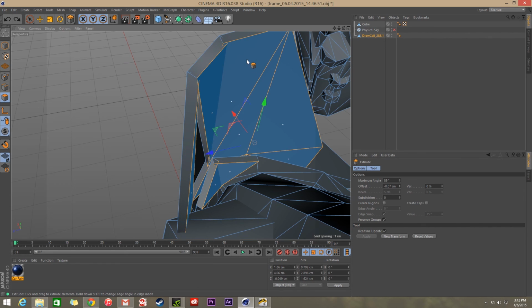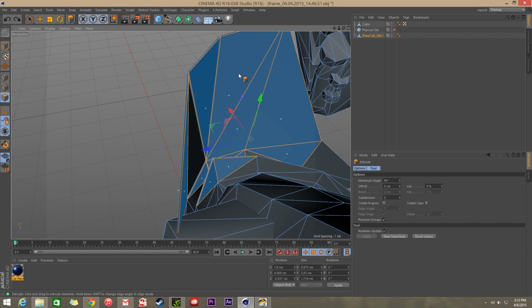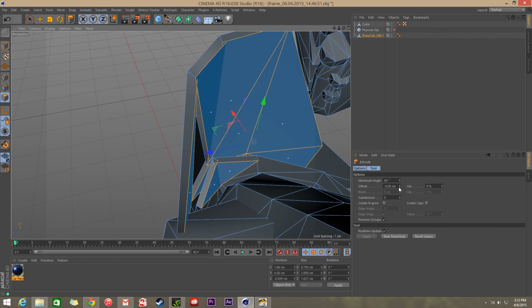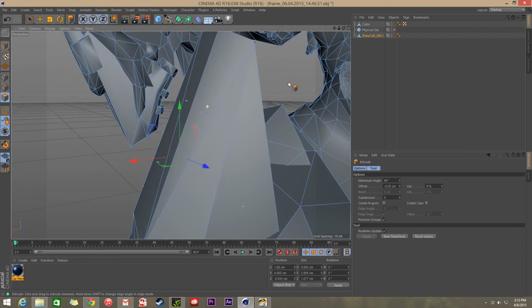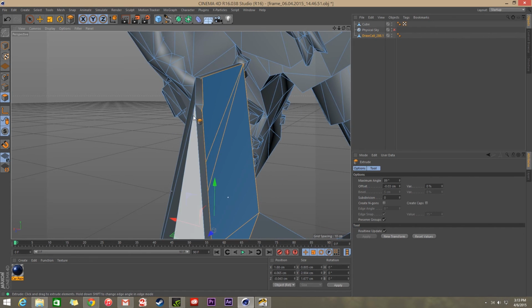Now that we have this selected, we're actually going to let go, and we're going to head over here, and under our selection panel, we have our attributes area. Now you might not be seeing this if this lock key is on. So if this little lock button's on, just make sure it's unclicked and then undo this selection and try again. And that's going to re-put these numbers in there. So what we're going to do is set that to not minus 0.06. We're going to set that to minus 0.03. And that gives us just a little bit of depth, just a little bit more geometry to look at here.